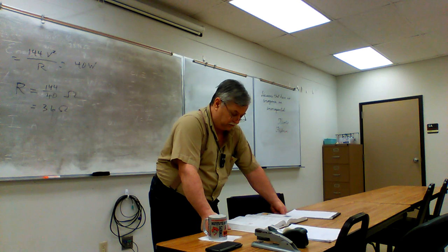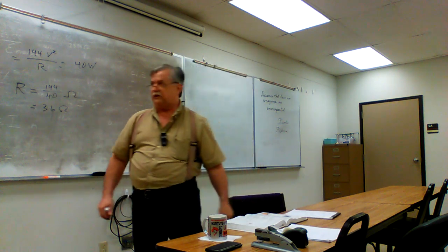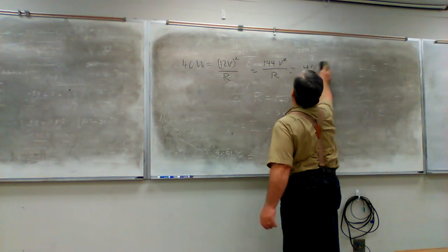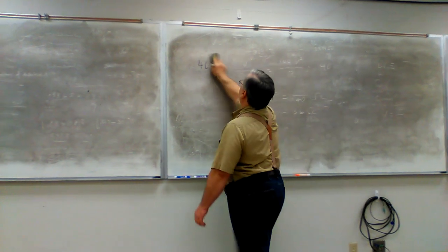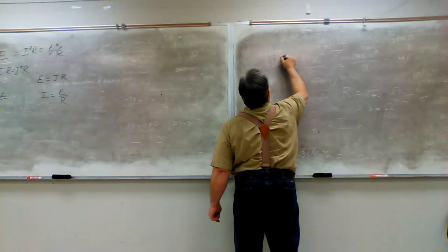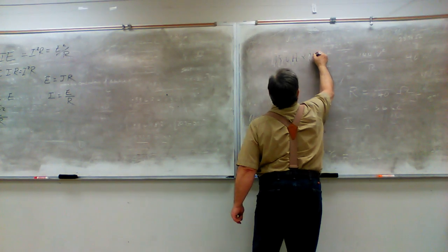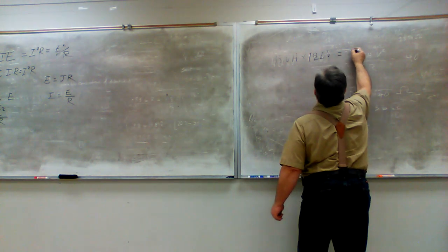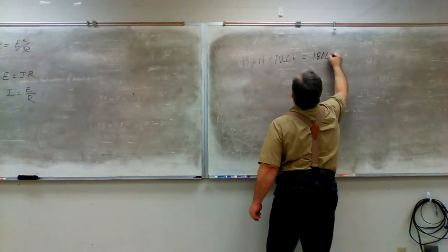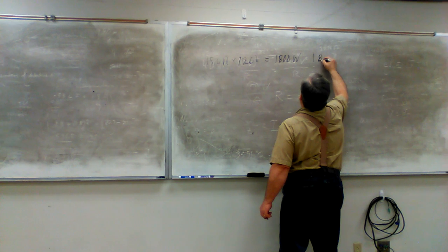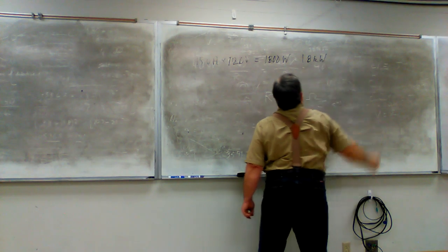So, 15 amps times 120 volts. Who's got their calculator out? That's 1800 watts, or 1.8 kilowatts, right?